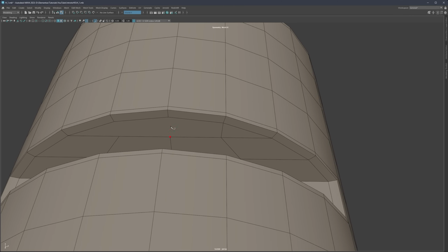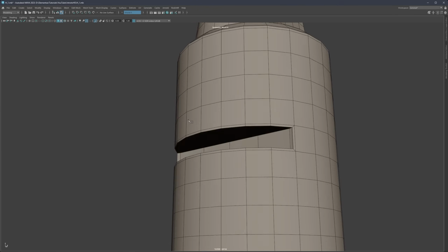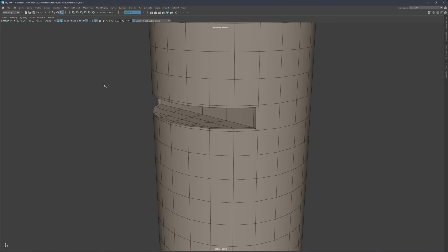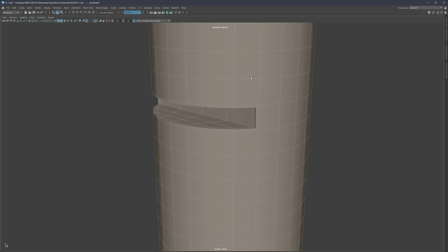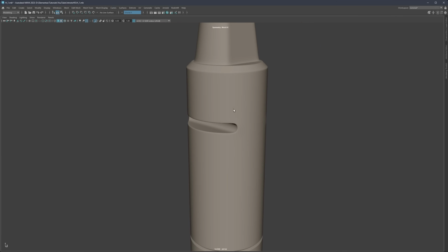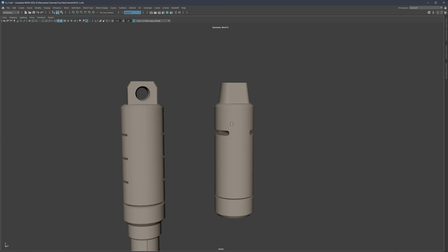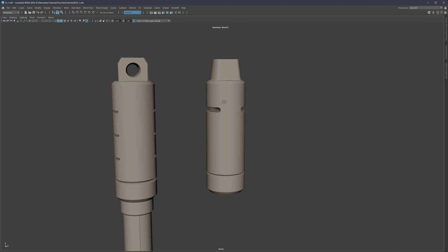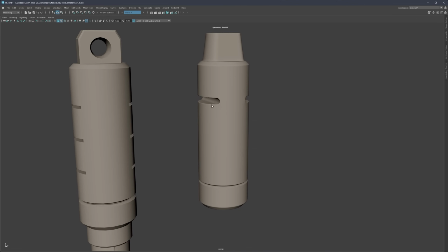So just right click to confirm everything. And now we have all these edges connected with all the proper edge loops, and then Q to exit the multi-cut operation, and right click, go to object mode, hit 3 to subdivide preview, and there we go. So this is now going to be, let's say, the detail that we can have based on the surrounding topology.